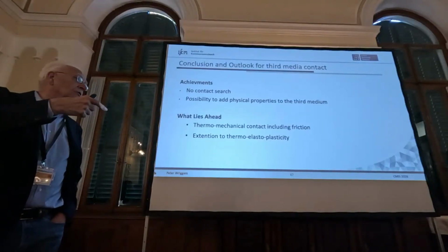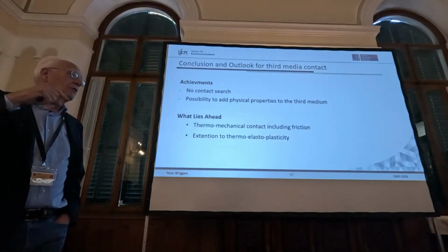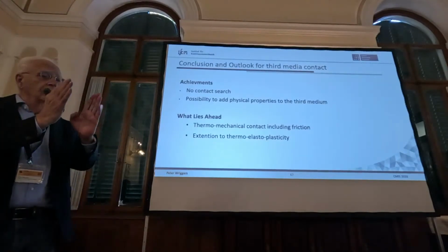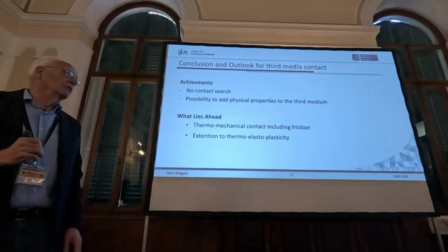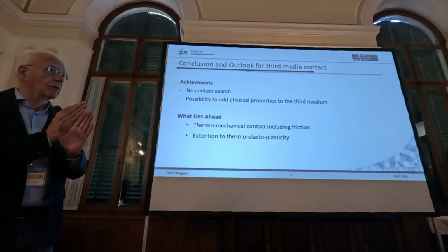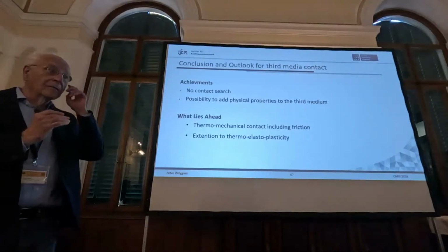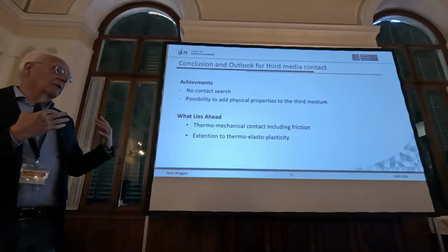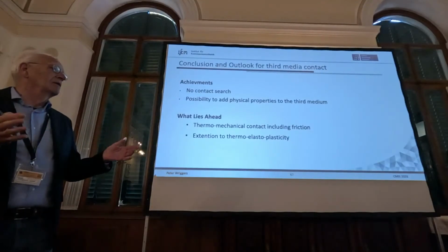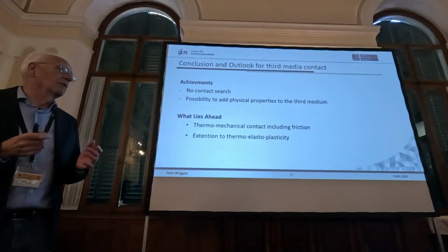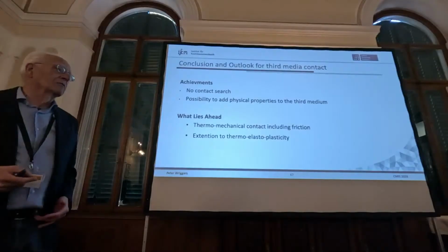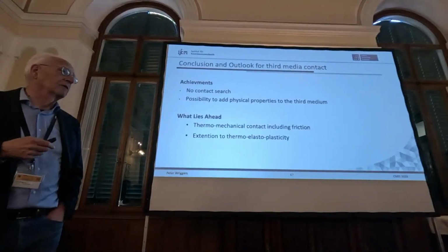From the theoretical point of view, of course, as gamma goes to 0, the gap also goes to 0, because then the log term only picks up if you're very, very close to the contact line or contact surface. This is fine, but we are limited by the computer precision, and this is why we cannot use a very small gamma. You could think about some tricks, but that's it.